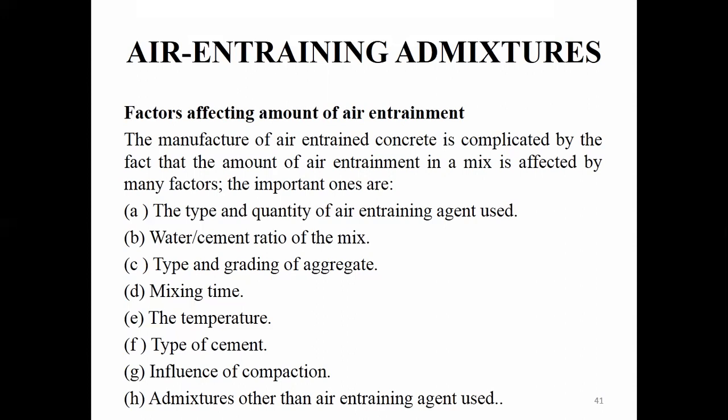This is also one of the important points because the amount of air entrainment depends on the elasticity of the film of the bubble formed. Bubble means that an air bubble will be formed, right? Over that there will be some film, one layer will be forming, that is called a film. So this will influence the elasticity. So the surface tension in the concrete will get reduced. Can you understand? Whenever you are incorporating some air in the concrete, there will be some air bubbles, right? Over the air bubble, one thin layer will be formed.